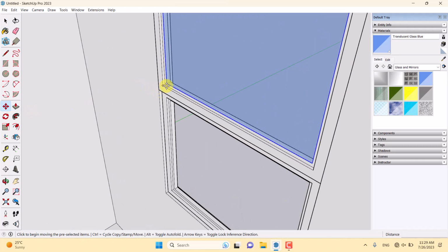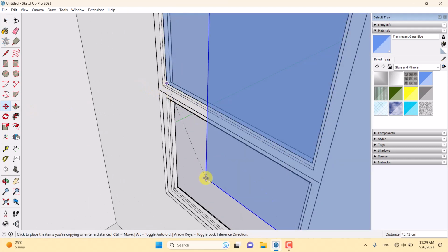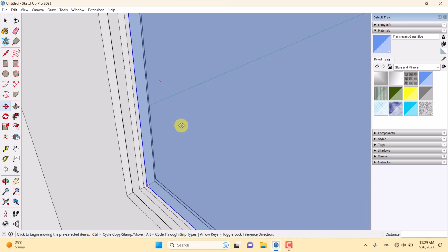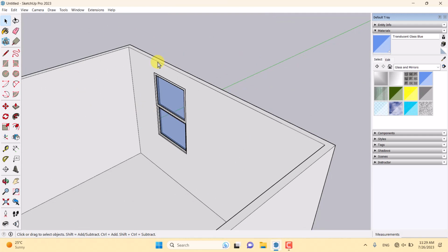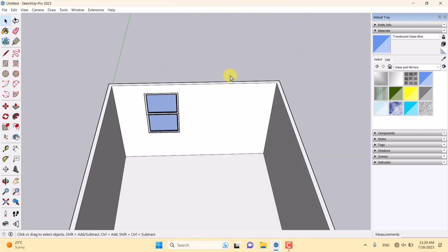I'm gonna create some type of kitchen with the living room in here. For this reason, I'm gonna use the rectangle box again and draw a rectangle with some dimension about 400 to 60 centimeter. Now I'm gonna push it a little bit to the upside, about 90 centimeter. So we have some tall cabinet in here, so I'm gonna move it a little bit.